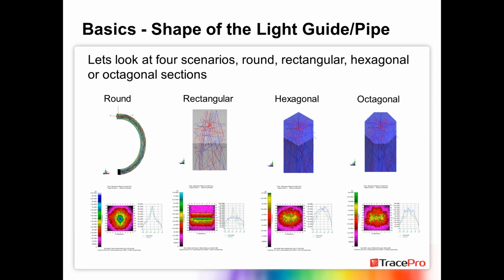Okay, thank you. Next question here. Is there a way to change the bend radius instead of segment/control points in the interactive optimizer? You can add more segments, and in that case, you can then specify a longer length, or you can specify a different radius along different segments. So instead of just having to change a control point, you can also specify that a particular segment is of a different type. It can be straight, it could be a spline, it could be a conic, and you have multiple ways of increasing the flexibility of what that light pipe does by adding more segments and more control points.